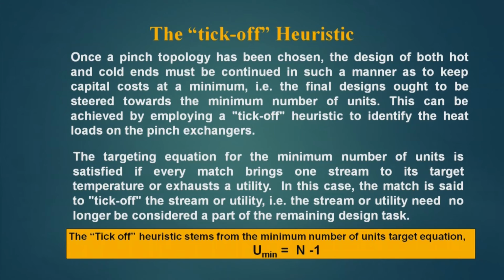That means, while doing targeting, we will see that at one go the maximum heat of a stream should be transferred to the other stream. The targeting equation for the minimum number of units is satisfied if every match brings one stream to its target temperature or exhausts a utility.